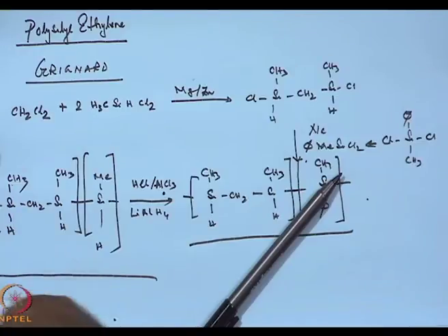So, what you can do is dissolve these polymers in a suitable solvent, then draw fibers from it. There are various standard techniques available for drawing fibers from polymer solutions. Get the fibers, pyrolyze them, and you have silicon carbide fibers.